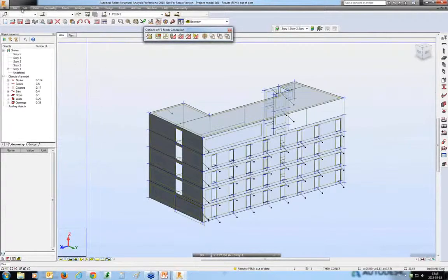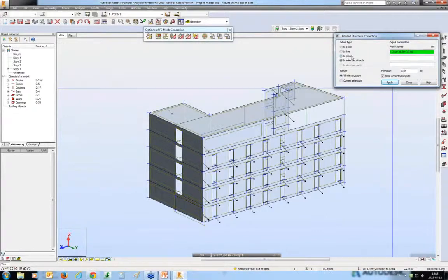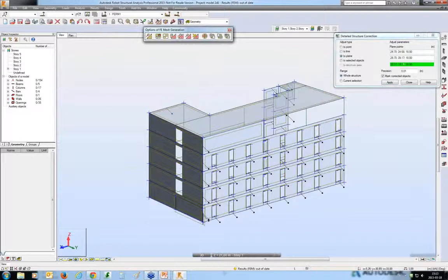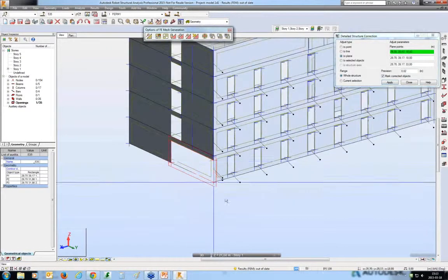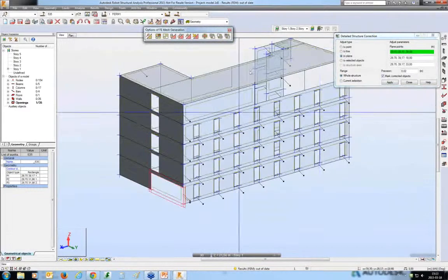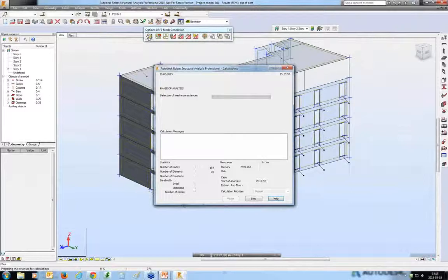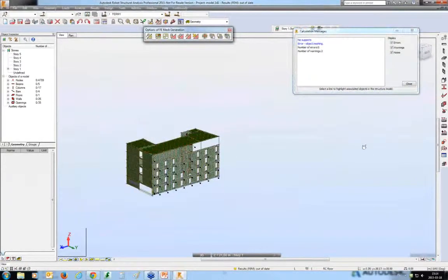And okay, running the detailed correction option, I should indicate the plane as I did previously, but I should also enter the right precision. Okay, this time it is 2 centimeters, slightly more than the error that I made in the geometry. Okay, so let's mesh it again. Yep, that was not intended, but actually that may be a good situation that it happened.